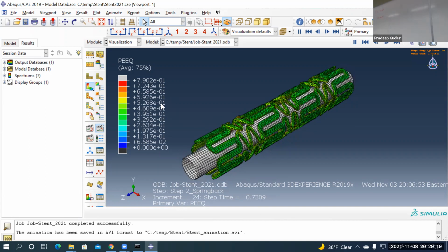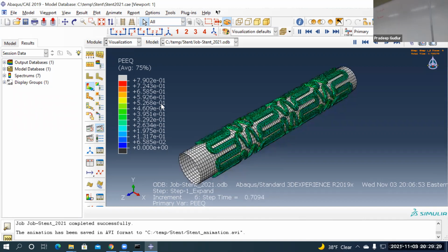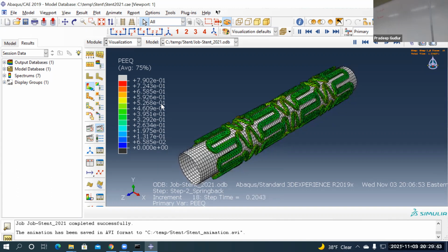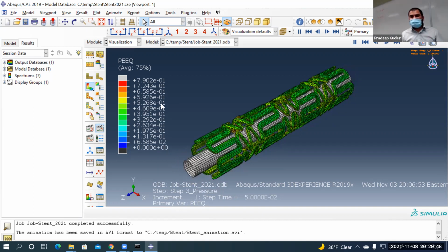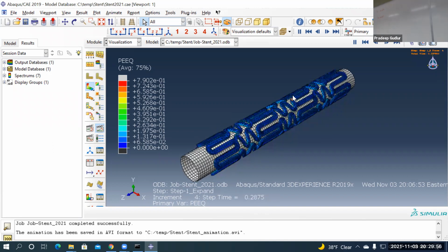Is this, these values, are these based off of that, Poisson's ratio and whatever number we put? No, this is equivalent strain. So if anything greater than, so this is a good measure. You don't have to compare with another thing. So if it's greater than 0, it can't be negative. It's equivalent. So if it is 0, means it has not yielded at that location. Anything above 0 means at all the locations it has plastically yielded, and it's retaining its shape because of the plastic deformation. That's why we are looking at PEEQ. It's retaining its shape. It's not going down.